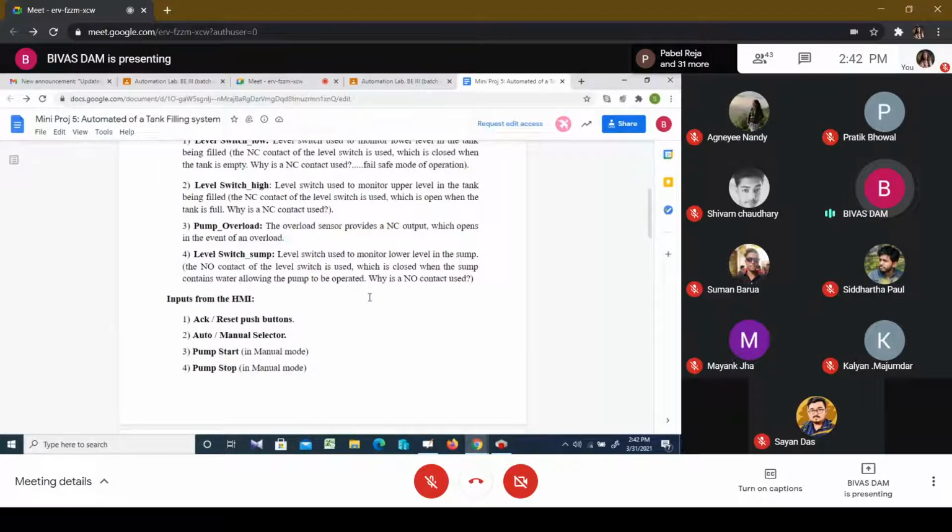Now, by the way, another abnormal situation may occur. Say there is some leakage in the pipeline, or the pump may not be operating properly. So what may happen is normally we know that to fill up the tank, a maximum of a certain T amount of time is required. Now, if within a certain allowance from this T, that means let me allow T plus n amount of time, so T plus 5 amount of time.